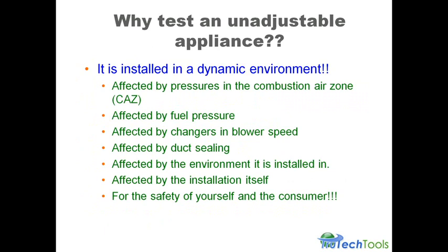All of a sudden it gets to the point where the blower overcomes the combustion air and it's back spilling into the house. Could be affected by duct sealing. Maybe you're sealing up the supply ducts. All of a sudden the air that the furnace is using for combustion, you just cut it off because you sealed the supply duct up, and the hole that was in the supply duct was giving you the right amount of air in the room.